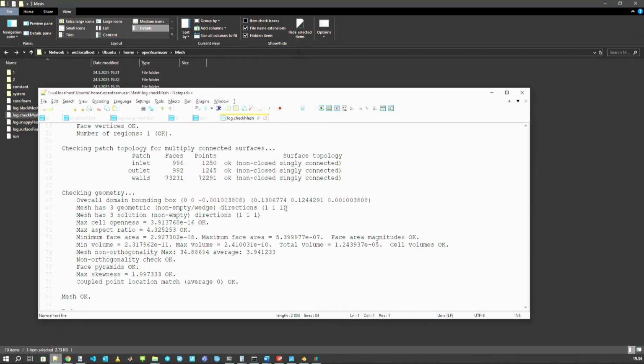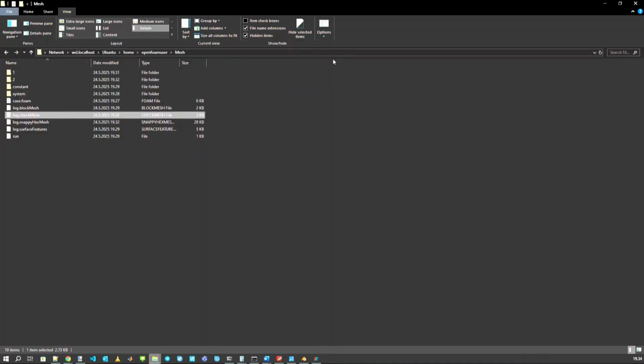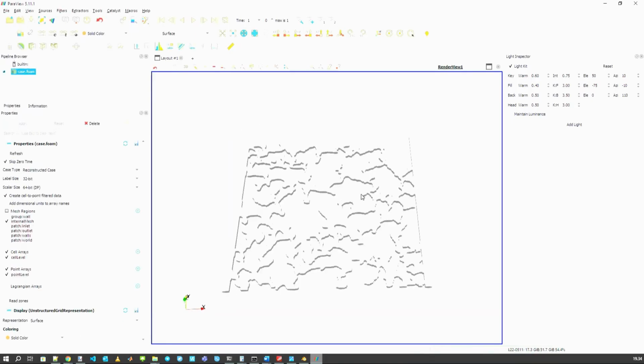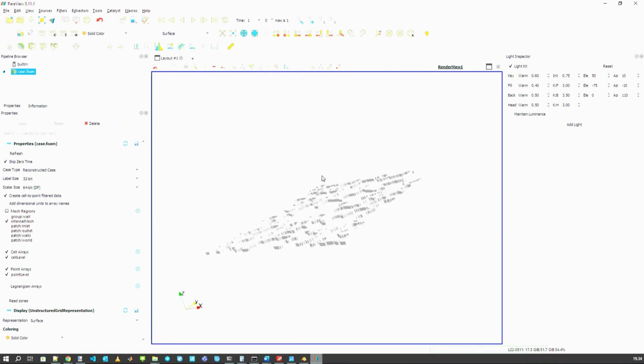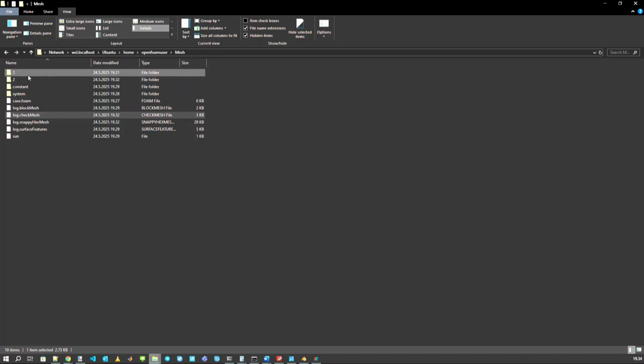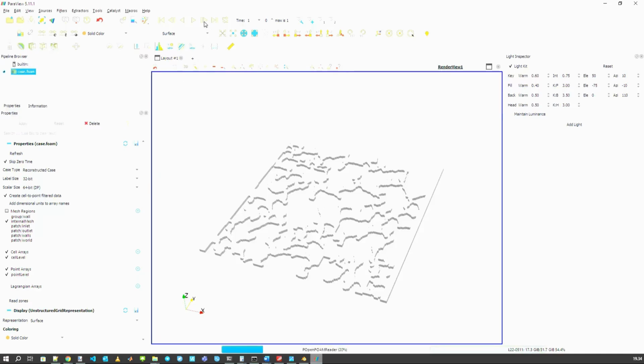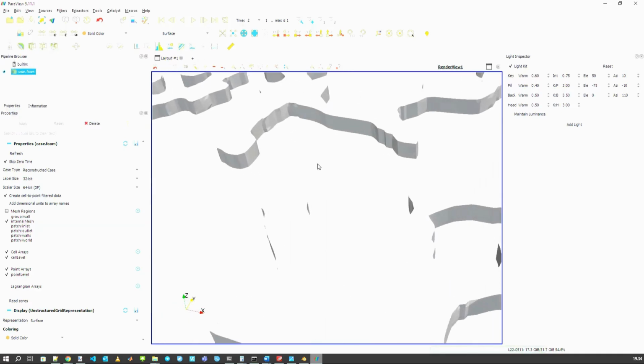As I mentioned, you can easily change the dimensions. We will reach that point, but first let's take a look at the mesh itself. This is the geometry that was created using snappyHexMesh and the workflow we introduced here. Two folders have been created, the first and second castellation layers, so you can move between them. As you can see, some curvatures have been captured in the second phase.